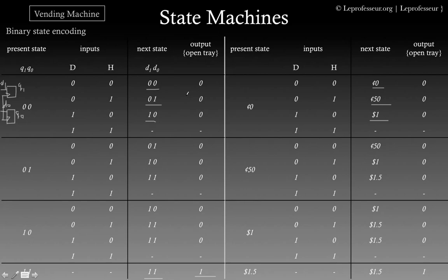So in practice, it is best only to change one bit at every clock edge, especially for the state, because that's the inherent structure of flip-flop design, how D-flops or other sorts of flops work. They suffer from metastability, and if the flop goes into metastability, we can't rely on the output. We are not going to discuss all those things here, but just to give you an idea to be aware of what kinds of encodings there are.